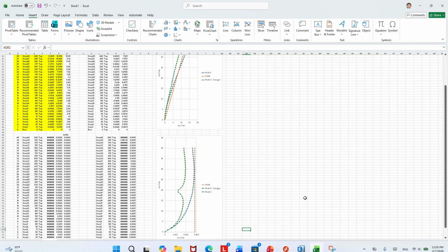The ratio should not be more than this, our guideline, H over 350, L over 350. 350 is the slenderness ratio. So the first model, you see that? Relatively severe, right? Once we add the outrigger, those numbers actually all push to the left. So it shows that it properly meets our criteria.